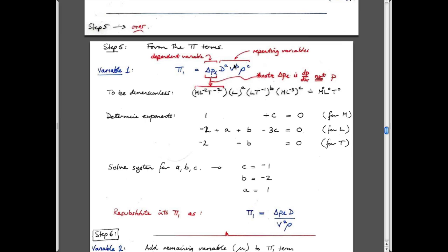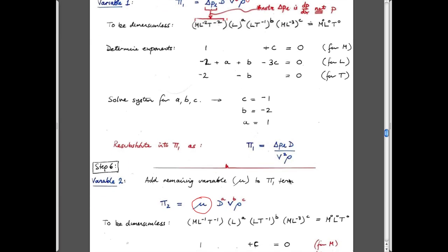And you just go through this formula where this one is multiplied by 1, and the remainder of these are multiplied by some exponent that we don't know. And so Buckingham Pi, all it does is give you the magnitude of these exponents, so that when you multiply this thing out and substitute back these exponents, the resulting term is dimensionless, as it is here. And so this term is basically an Euler number, right?